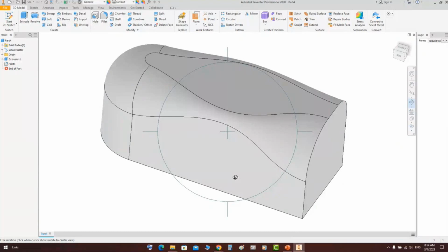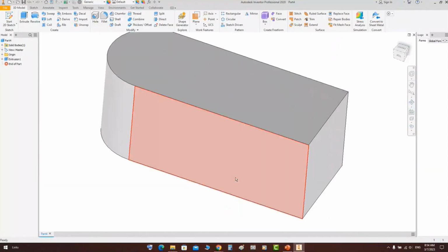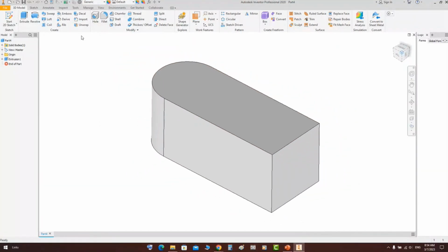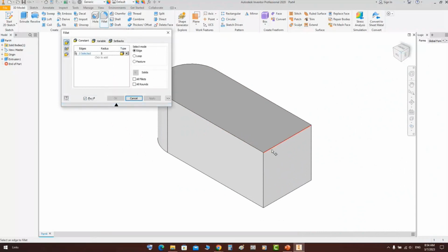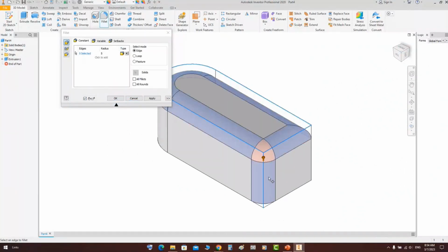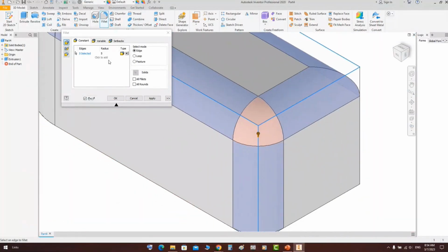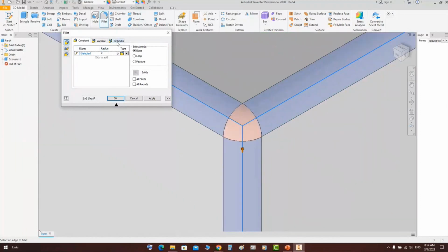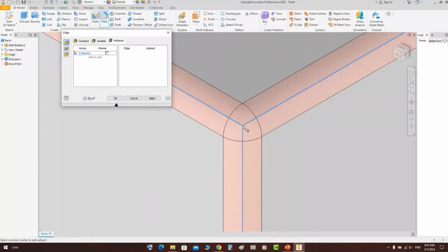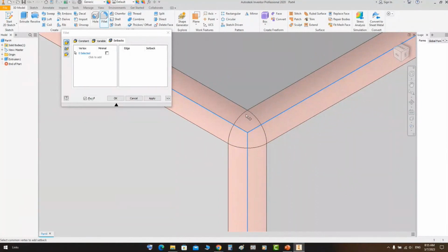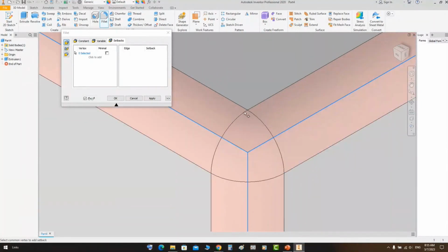You can make or use the different value feature. So let's come back to the 3D model and create another type of fillet. If you select the corners, for example, those 3 corners like that, and let's define this value as 2. Okay, and if you come back to setback, it gives you the ability to change the end of the intersect between the 3 edges, and it gives you this result.